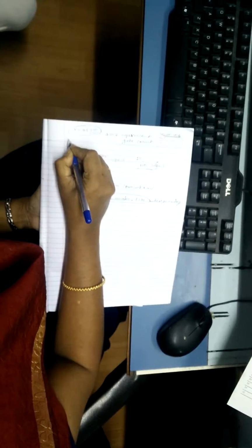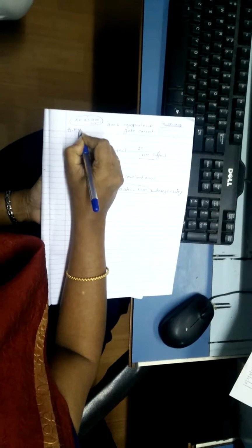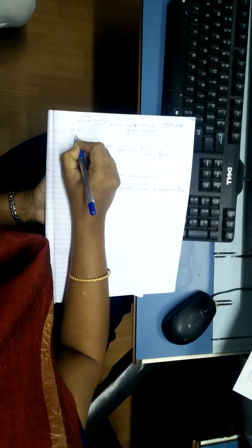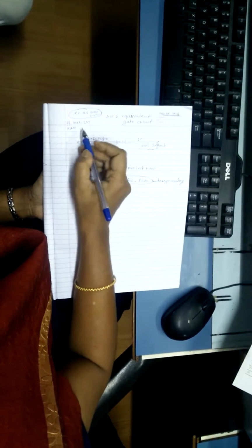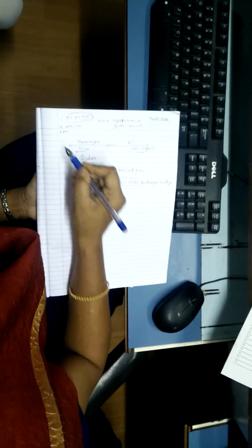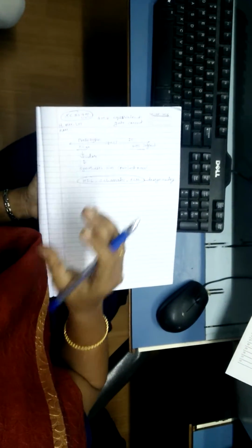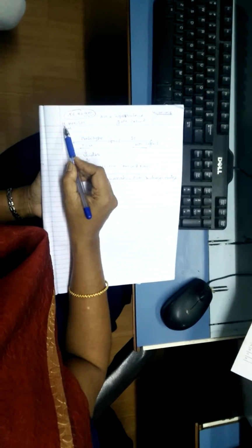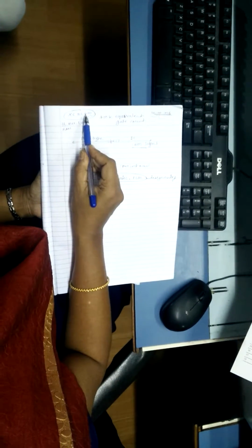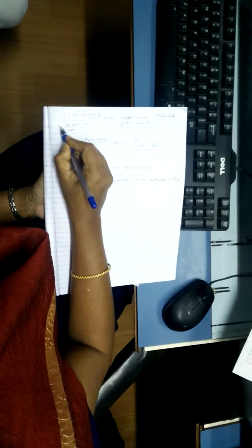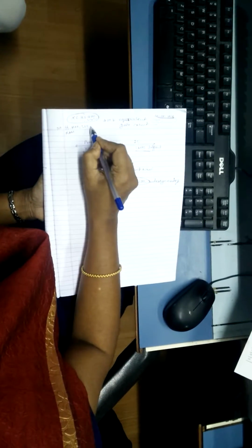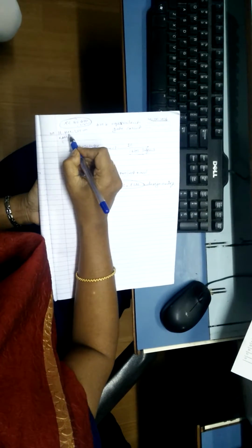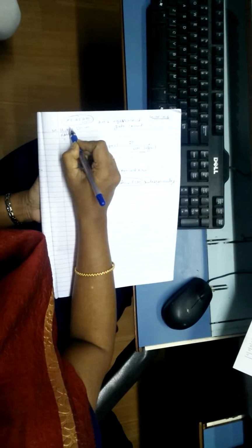You have flip-flops, you have muxes, you have lookup tables, you have RAM memories. These are the primitive elements, or basic components or resources, of an FPGA. Suppose this particular chip has 100 flip-flops, some 500 lookup tables, 4 RAM memories, and something like 150 muxes.